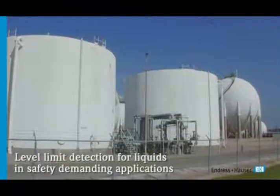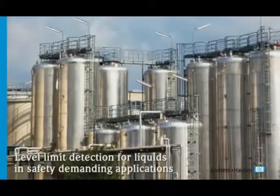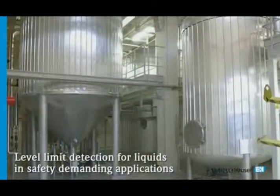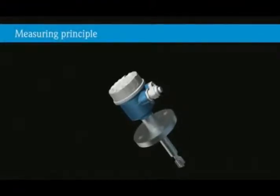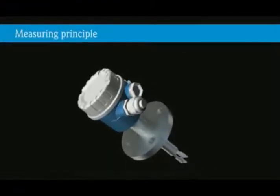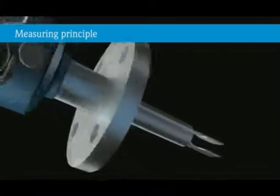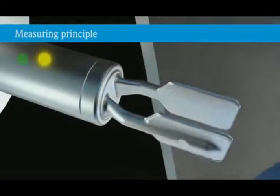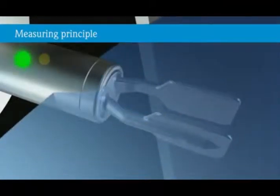In level limit detection, fast, safe functioning and availability are of high importance. Small problems can cause devastating effects. Liquiphant, the active level limit detection with a safety window. A sensor in the form of a tuning fork is excited at its resonant frequency. The drive works piezoelectrically. The oscillating frequency or the amplitude changes as the fork enters the medium. The change is analyzed and translated into a switching signal.